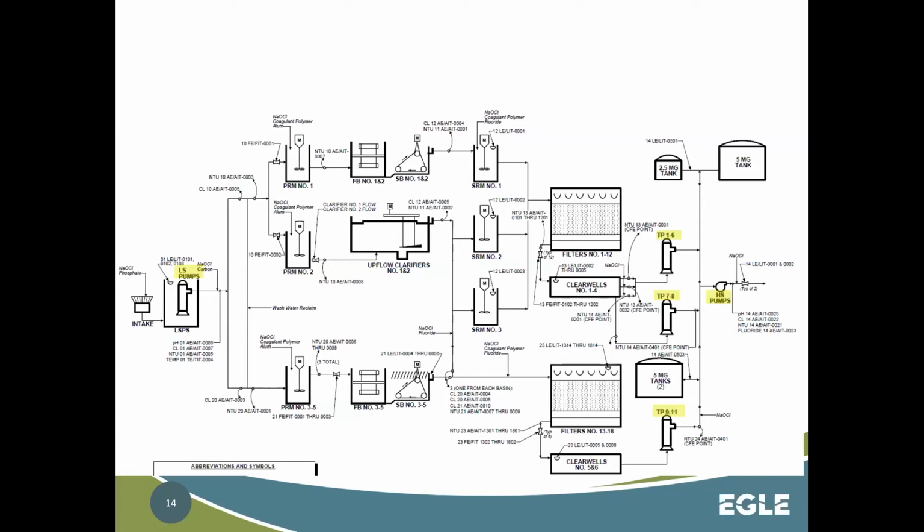usually different pressure districts within the system, right? We're looking at lower elevations, we'll usually see the highest pressure at that low elevation. So we need to make sure, by those inputs throughout the system, we're not over pressurizing those districts. And usually that's a control point on low elevations. High elevations too, we need to sustain the pressure there.